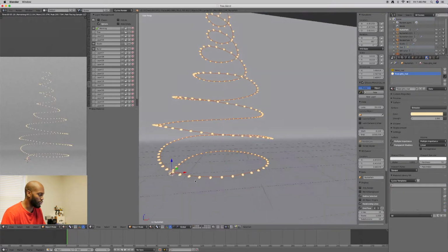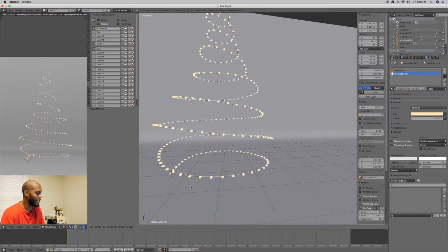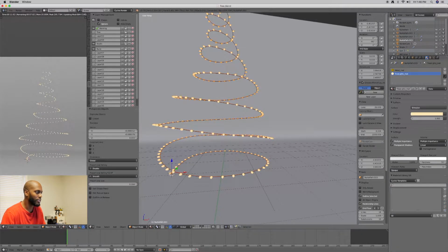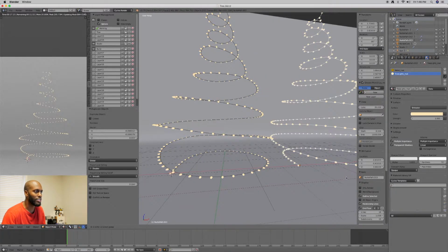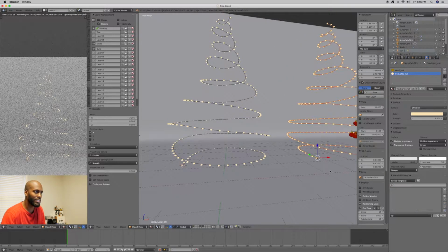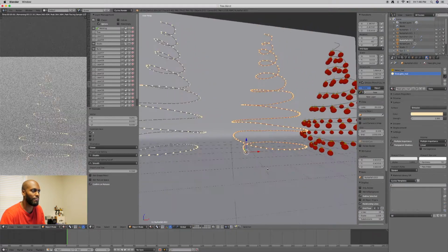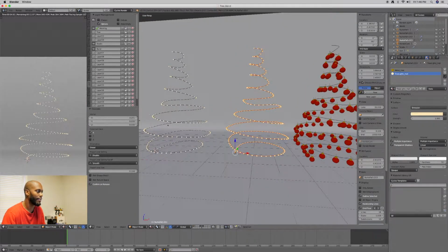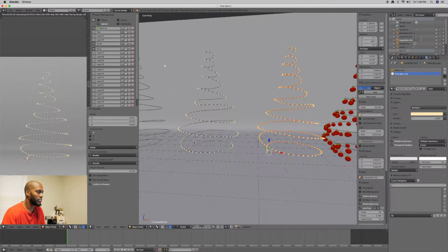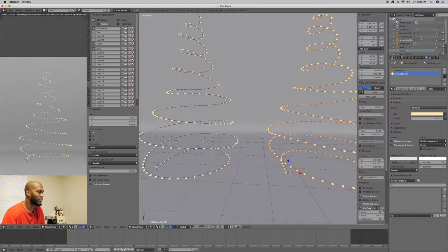We're going to do Control D, not Alt D, but Control D. Left click to lock it in, and then we're just going to slide this off to the right. So this will be one of our working layers, because essentially we want to use this to build our shape out and then duplicate the ply to the tree later. So we'll keep that as a working layer.